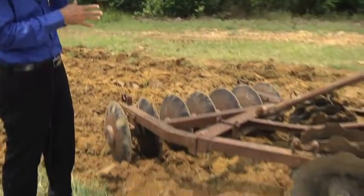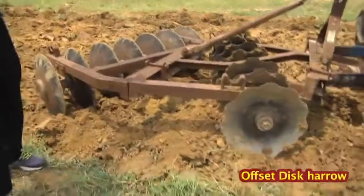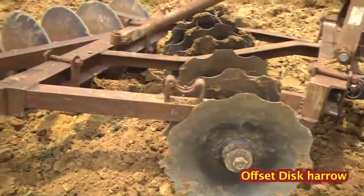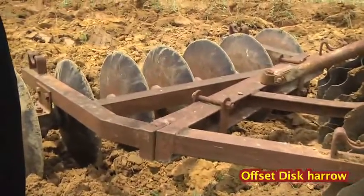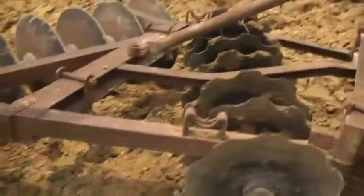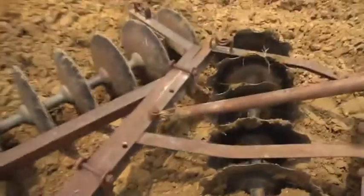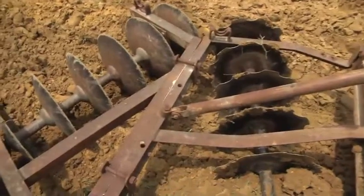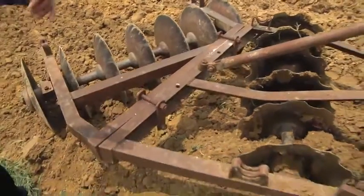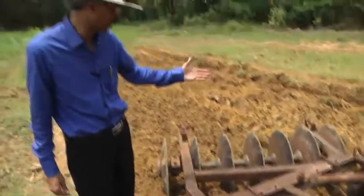This is one of these, which is a disc harrow. You can see that there are two gangs of disc on the same axle here. One set are notched discs, the other are smooth discs, and they are set at a certain angle with respect to the line of motion. Now, these angles are very important so far as the cutting of the soil is concerned. The notched discs help if there is a grassy field or grasses are there; they will cut those, and these will smoothly take the soil and put it onto the other side, as we have seen.